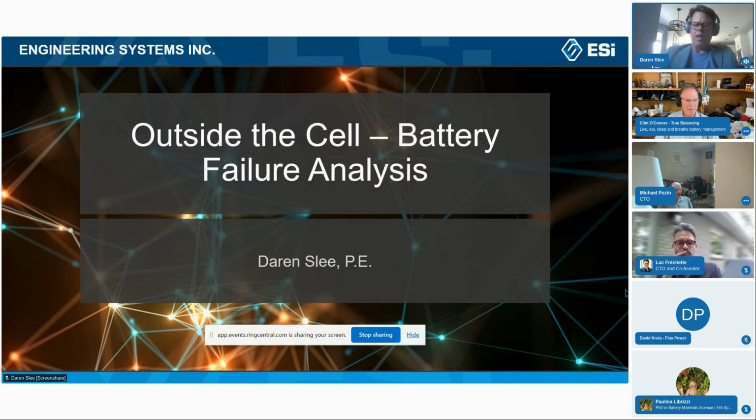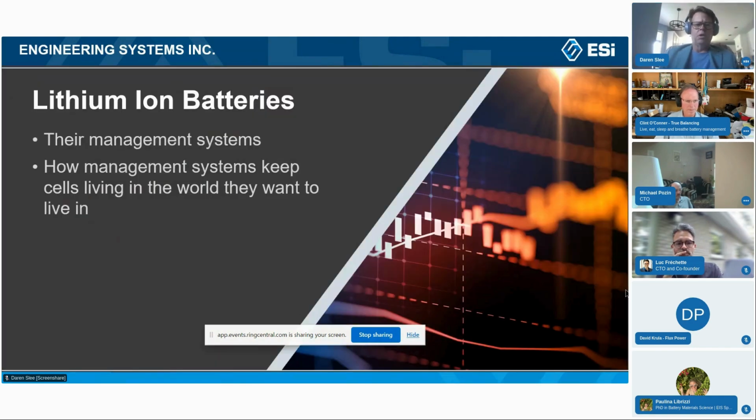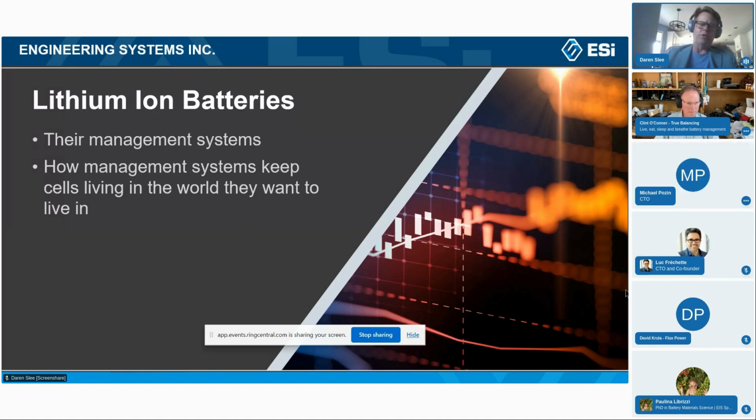I've done failure analysis for around 20 years plus. This presentation is about battery management systems, how they keep cells living in the world they want to live in. Battery cells have specific parameters, and I'm talking lithium ion here: the maximum voltage, the minimum voltage, the maximum current, both in and out, and maximum and minimum temperatures.